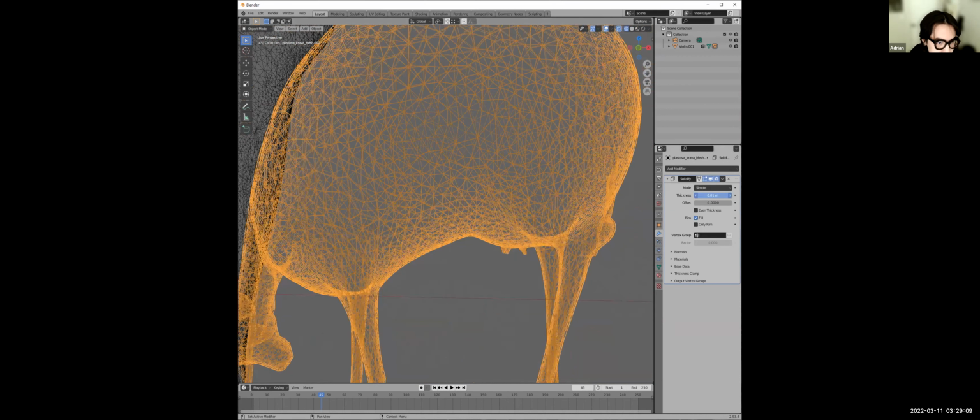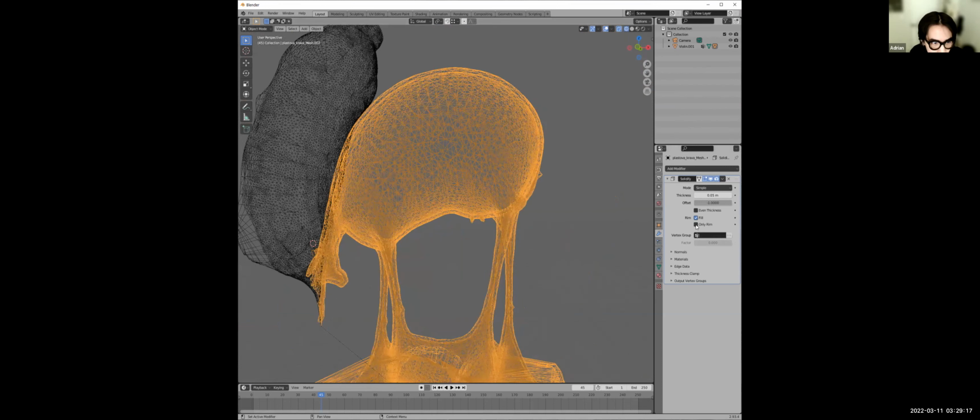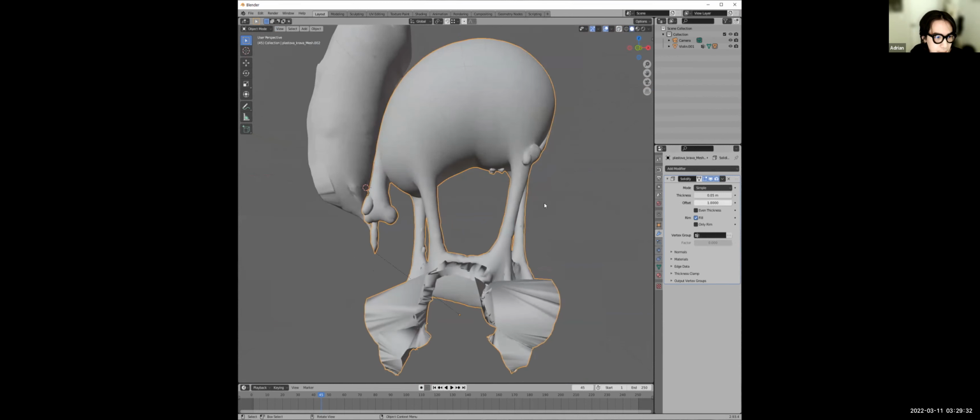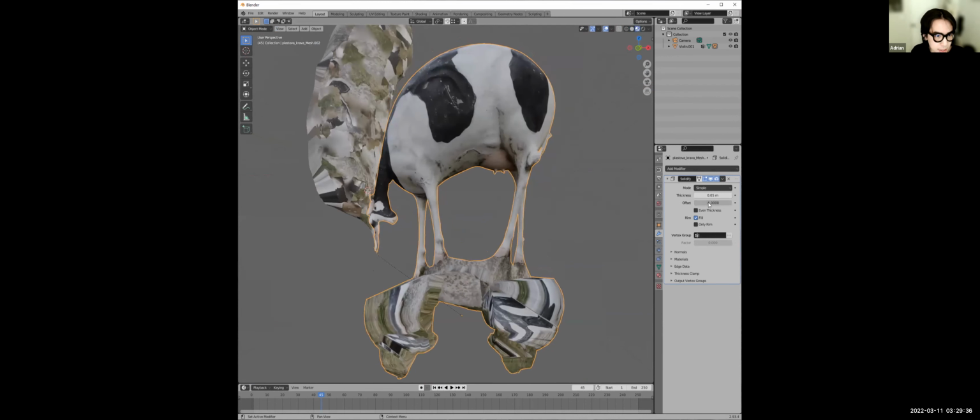And then the thickness you can add here, 0.01 meters, 0.05 meters. It'll be even thicker, a very thick wall, 0.5 meter. You can make sure it's an even thickness. That doesn't really work that well with something like this. You can make sure the offset is, I think, negative. So now it's 1, so now it goes in the other direction. And then this one goes inside. It's all up to you what you want. I think you can play around with these tools. You can do only the rim, but just the default settings usually is good.